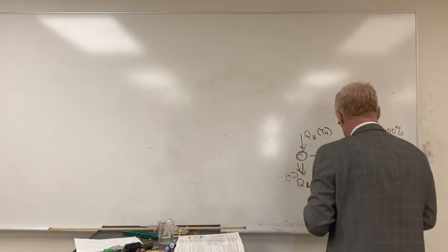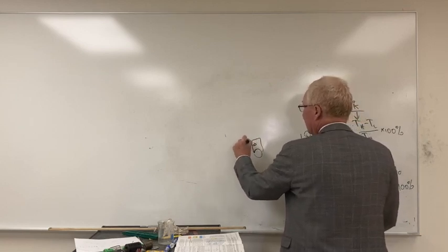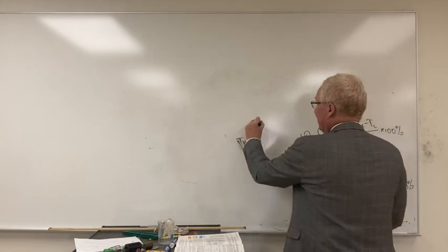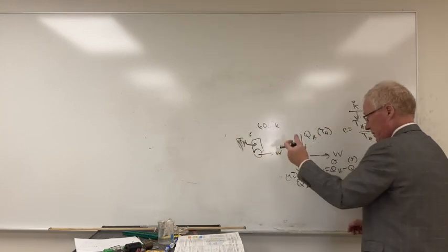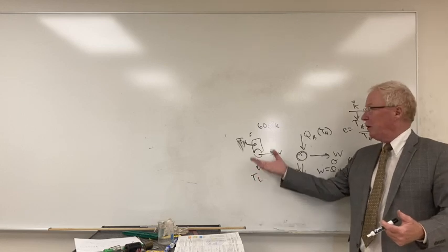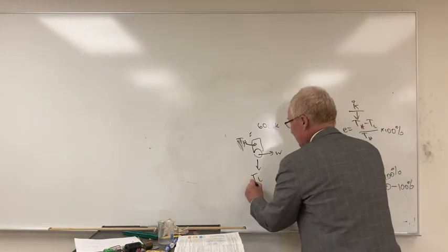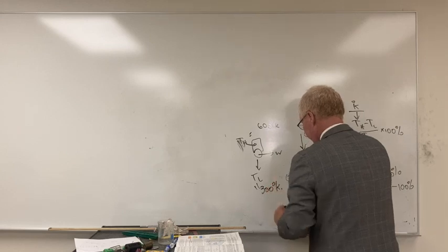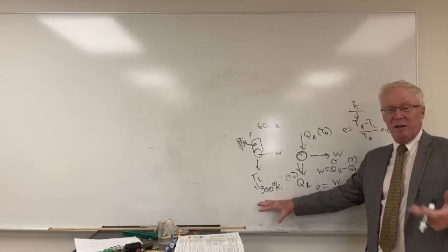All right, so if you have an engine, say a car engine, you apply heat, for the gas, T hot, the gas is hot, say it's 600 degrees Kelvin, and it does work to turn the car, make it go, but there's an exhaust that comes out. This has a temperature to it. Now it's not absolute zero, it's going to be colder than it was there, but it's relatively warm. If you ever feel the exhaust of the car, say it's room temperature, which is about 300 degrees Kelvin, okay? So you can check that yourself, that this is approximately room temperature. Remember, 273 is 0 degrees Celsius.